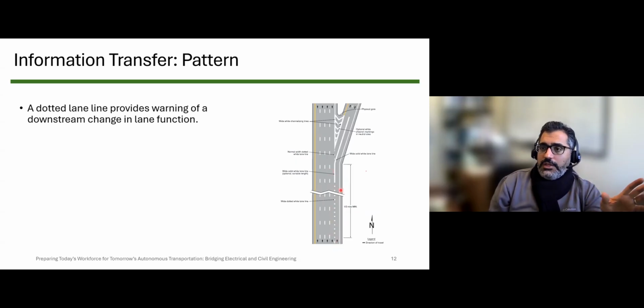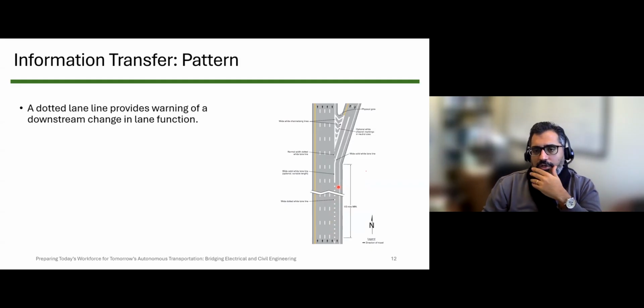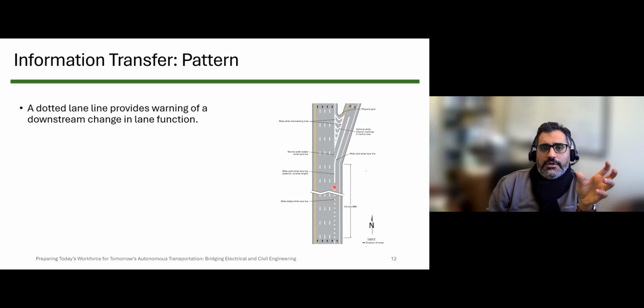Is it the only way that we communicate the message? No, we also add traffic signs, but again, think about that redundancy, that safety factor that we are considering in our design. And these are usually wider, so sometimes they are even called elephant feet because they are wider pavement markings. Again, another way to communicate the message.